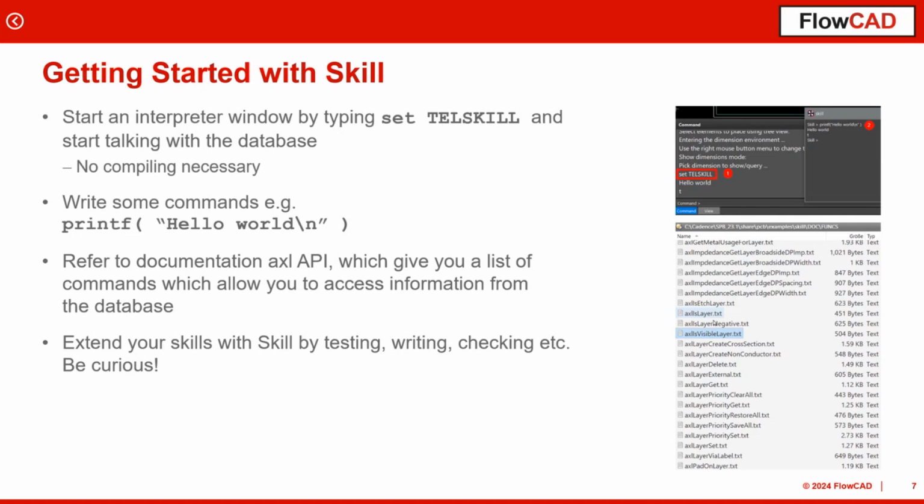So when it comes to accessing the database itself in terms of logic, part list, nets, physical data like traces and cross-section, you need to know what the APIs are, what the SKILL procedures are that I can use to extract those. They are part of the installation under share, PCB, example, skill, doc, funcs. Sorry, you don't need to remember the exact path. You will even find it in the documentation itself.